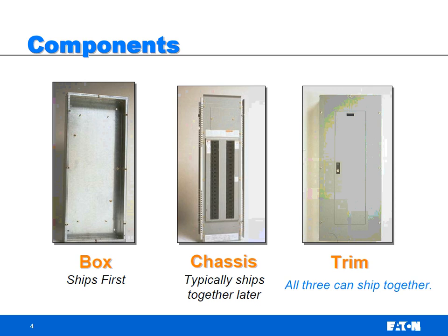So in your garage, hopefully you've got some kind of protection on there. But if not, along the edges in the wireways or the gutters is where the cables are. That's where the connections to the breakers are. And that's where the live electricity is that you want to prevent unauthorized people from touching.